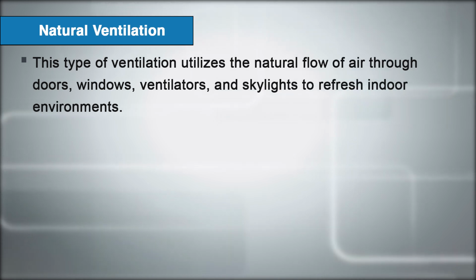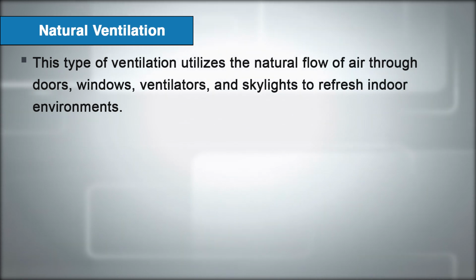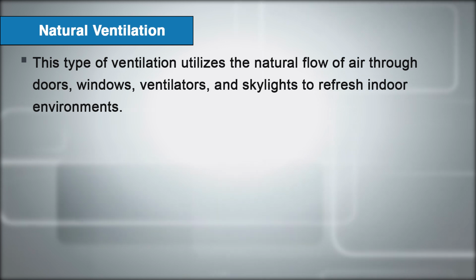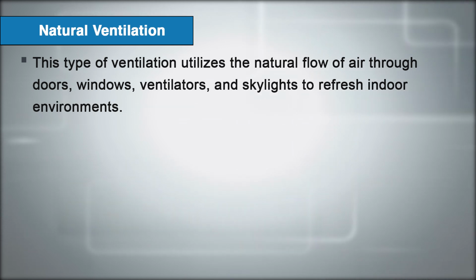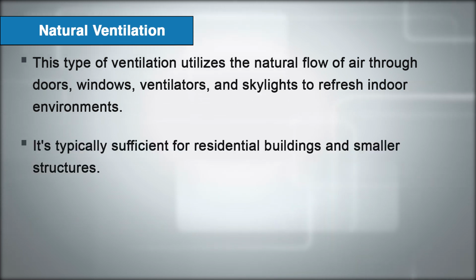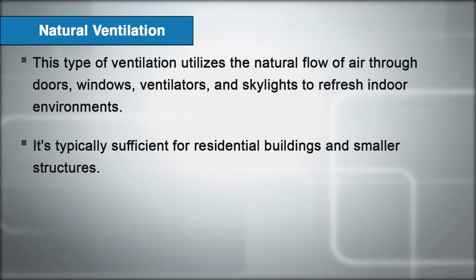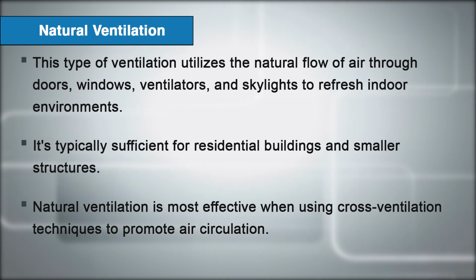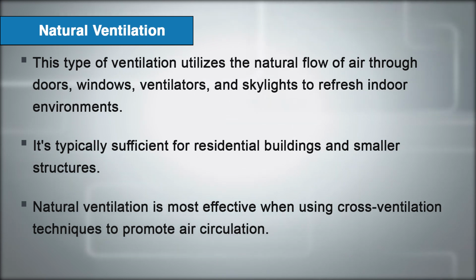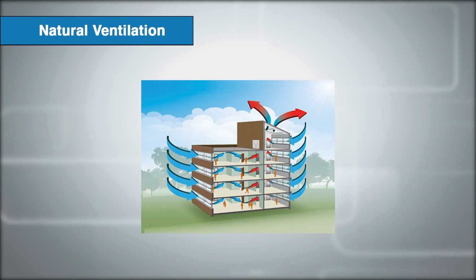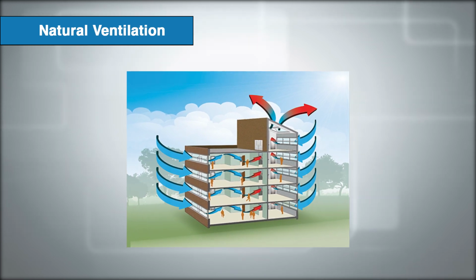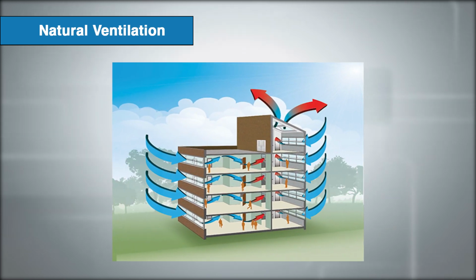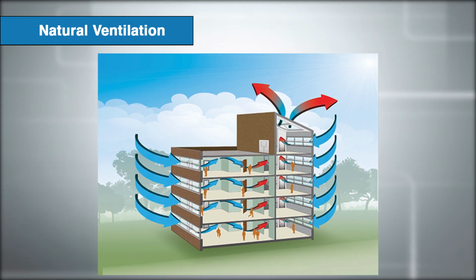This type of ventilation utilizes the natural flow of air through doors, windows, ventilators and skylights to refresh the indoor environment. It is typically sufficient for residential buildings and smaller structures. Natural ventilation is most effective when using cross ventilation techniques to promote air circulation. This method is cost effective as it does not require any mechanical equipment to maintain airflow.